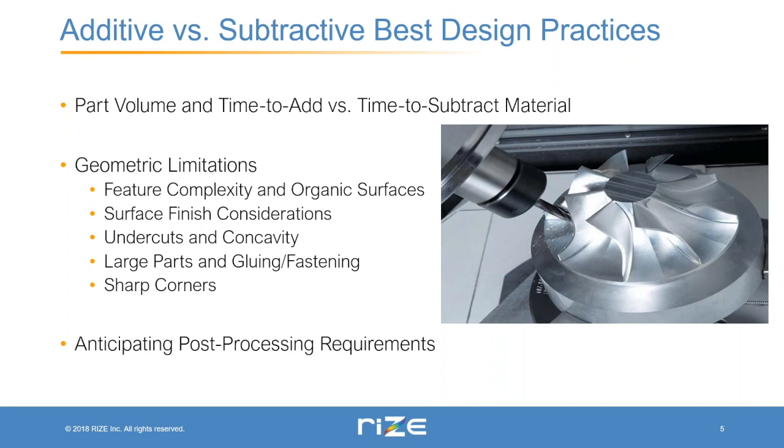Now with additive, in some cases, depending on the technology, it's also fairly easy to get a good surface finish, but there are also some special cases, such as very shallow surfaces, shallow meaning surfaces that are close to horizontal but not quite horizontal, and surfaces like these can produce somewhat stepped surface finishes that are not as smooth as you would get with a subtractive type of process.